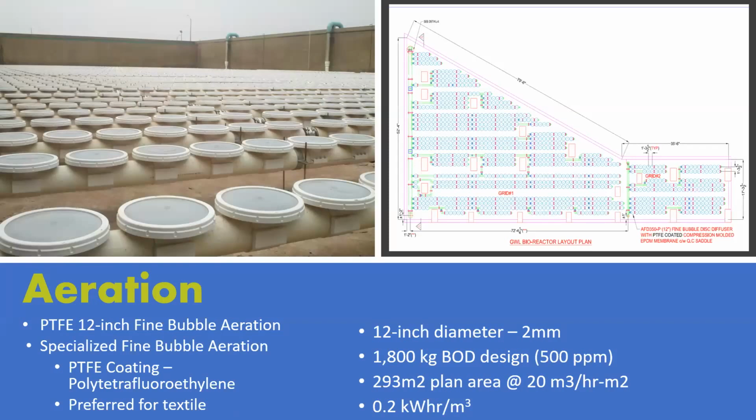Now, we haven't really touched base in this presentation on the use of PTFE, but in 99% of the MBBR applications that we design, we recommend PTFE. PTFE does an excellent job of protecting from biological fouling and inorganic fouling, and a much better job of controlling back pressure and creep over time.